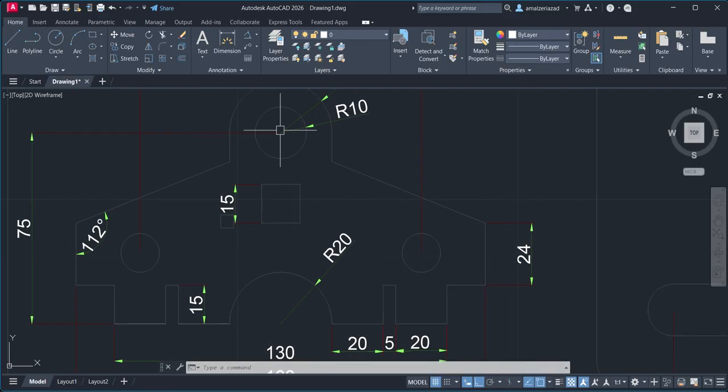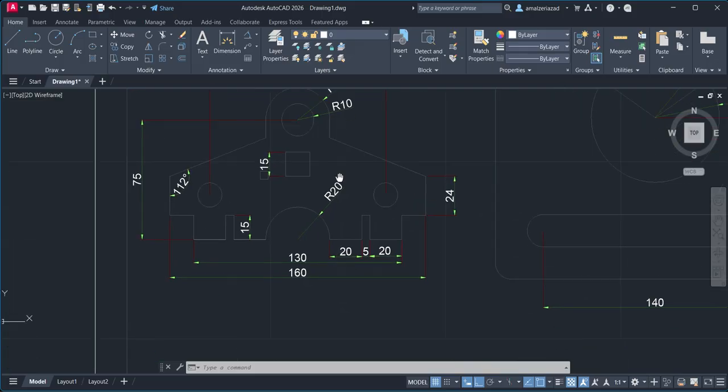Here also, if you can see, it is aligned central. If it is aligned center, the value of this is 15, right? So I have to take a line from here and create till here. You can do that also. As you know, the total distance is 160. If I take half, it becomes 80, so 80 will come at exactly the middle. But in that you have to minus half of this, which will be 7.5. So 80 minus 7.5 you have to do.